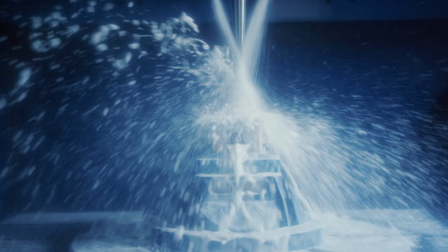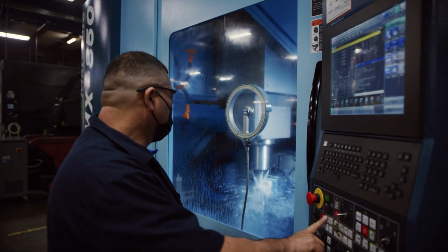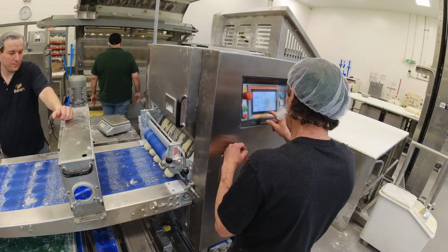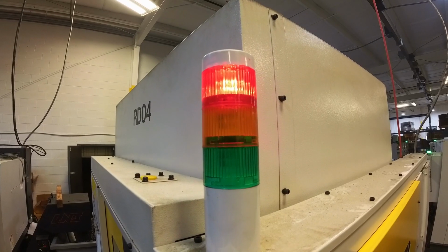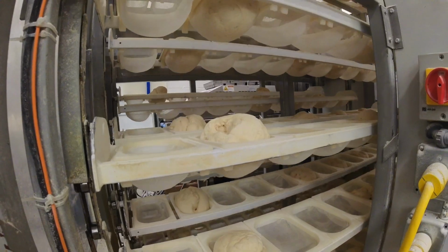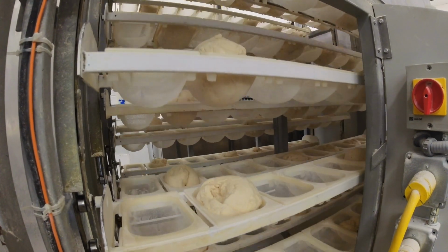If cycle time is one of your KPIs, you may need to perform time studies to observe and measure the time it takes to complete each step of the manufacturing process. This includes measuring the time from the start of a production cycle to the finished product. Assess variation in cycle times based on shifts, machine settings, operators, or other factors that could affect the process. This will help set a baseline for normal process variation.